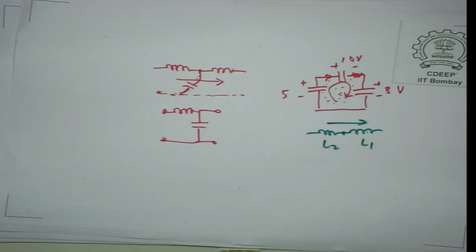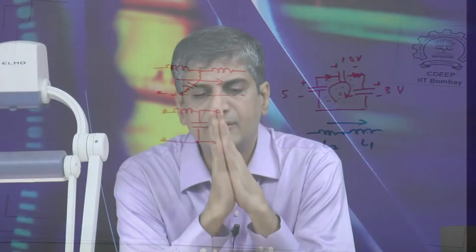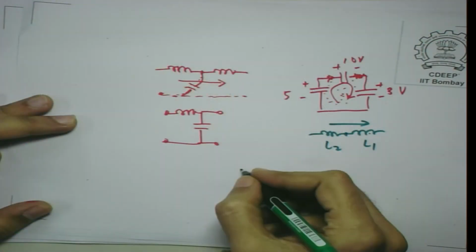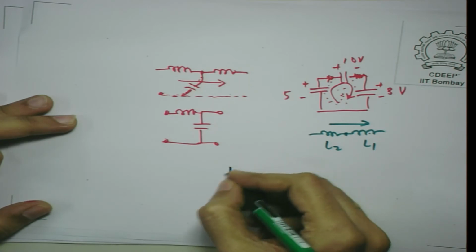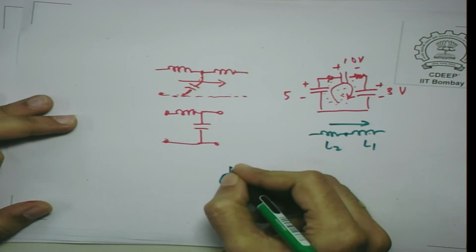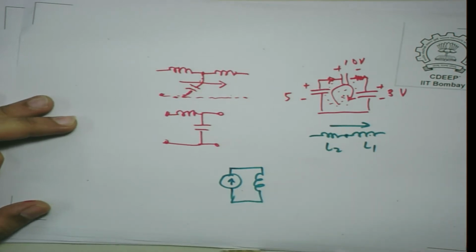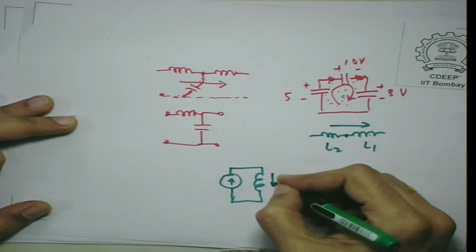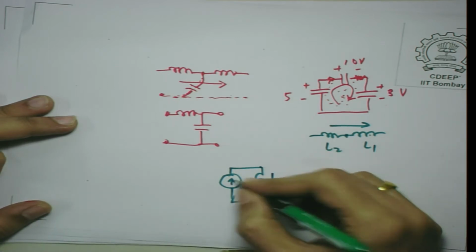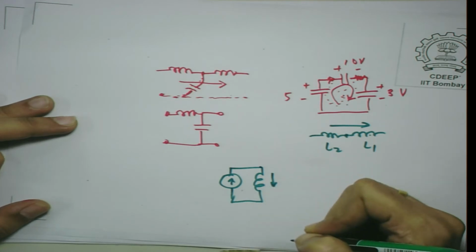This is also an important thing, because although in the circuits I have shown you, I have defined what my input and output is, some of the things which are proscribed, meaning not allowed, are these: if you are specifying a current through an inductor like this, it is generally not allowed. The reason is that you can allow it provided this current is absolutely consistent with this initial condition.